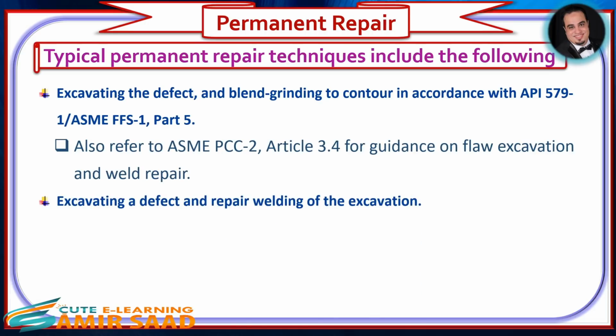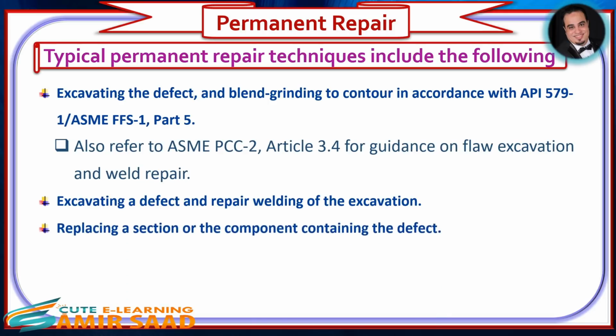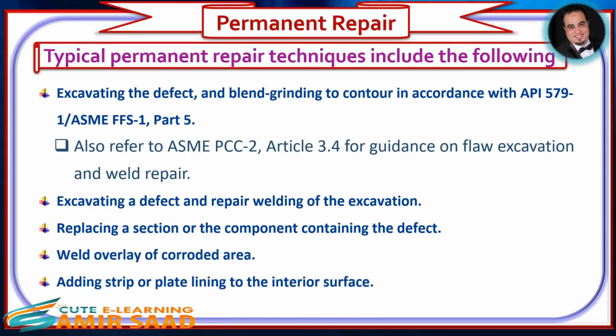Excavating a defect and repair welding of the excavation. Replacing a section or the component containing the defect. Weld overlay of corroded area. Adding strip or plate lining to the interior surface.